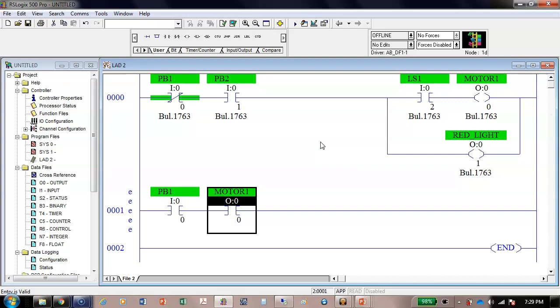And I'll show y'all as we move along how you can set this up before you even write your program. Once you've matched an address to a symbol, you can just use symbols from then on, which makes writing programs so much easier because now you don't have to worry with addresses. So this is like your contact list in your phone.